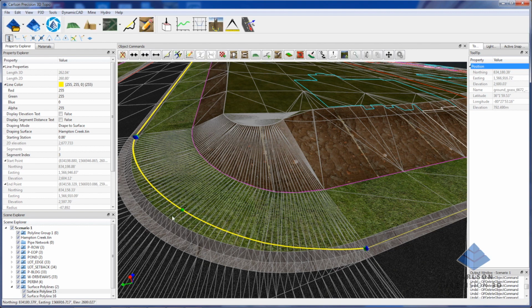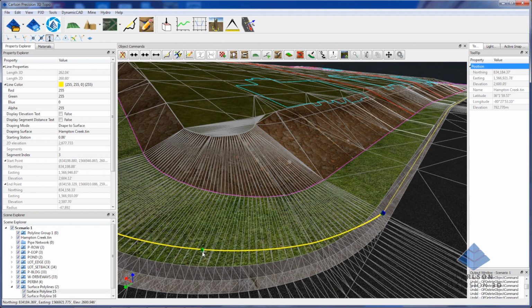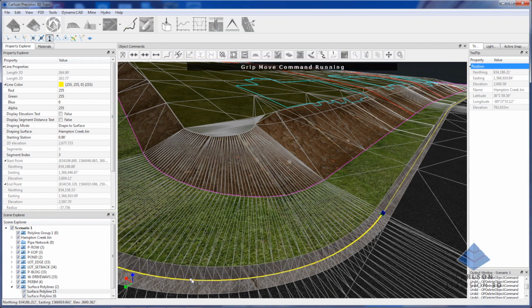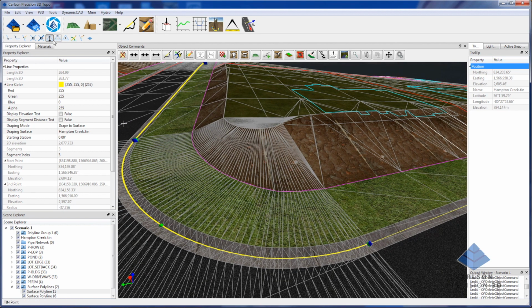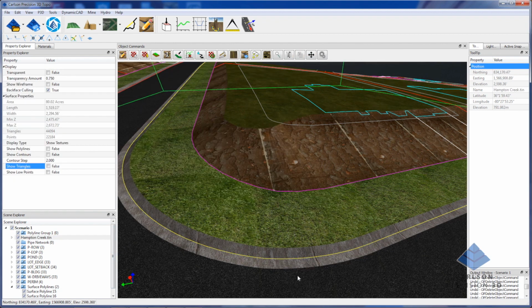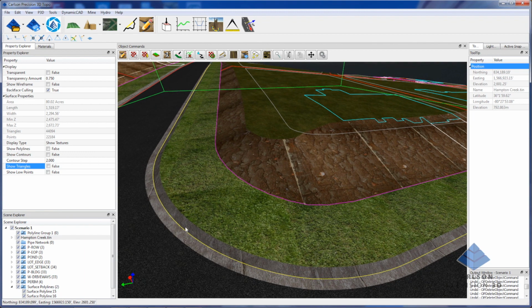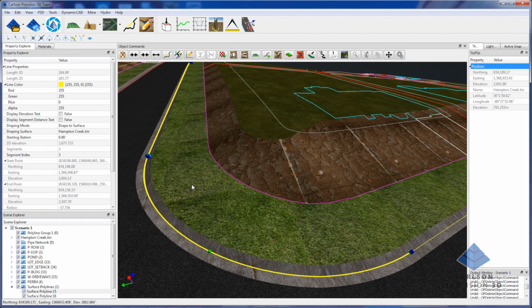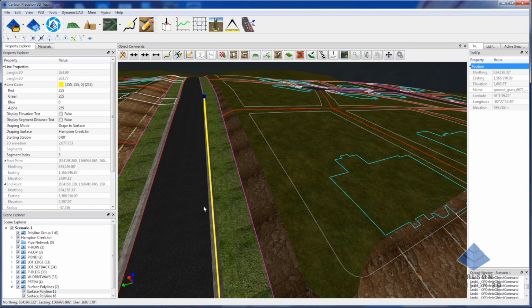There we go. And now what I'm going to do is turn that one off and turn on the vertex, or the face edge snap, and I'm just going to pull this down, and you see it snap right into that edge. And notice that we still have our minus 37.75. So again, that's a way that we can pretty easily extract actual coordinate geometry, because these aren't just tessellated lines; they're all straight line segments where appropriate.